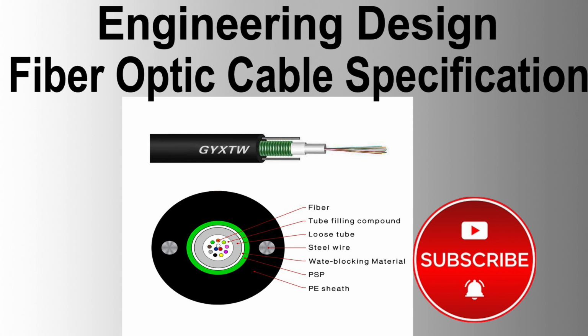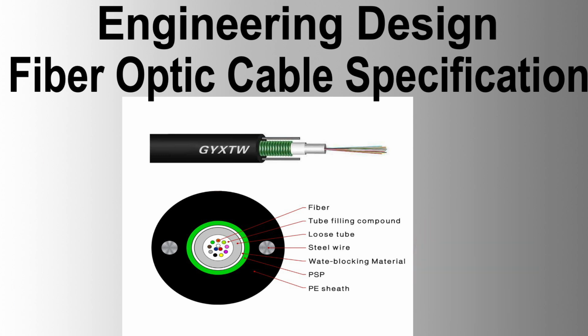Composition and function. A 2.5 mm GRP rod, subject to vendor design, placed in the center of the optical cable core, serves as both a tensile strength element and an anti-buckling member. It must be free of imperfections and stiff enough to prevent kinking at the minimum bend radius. Buffer tubes and filler rods.